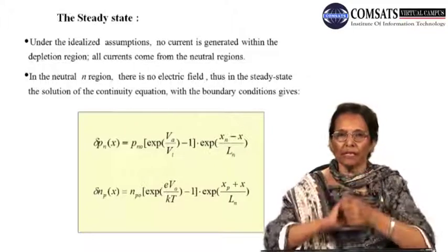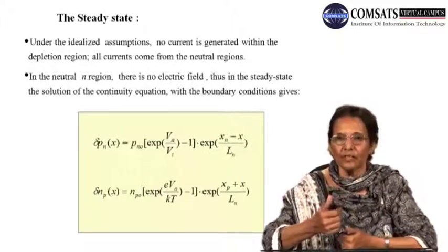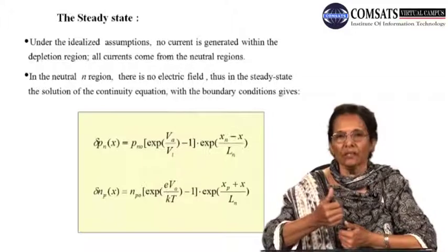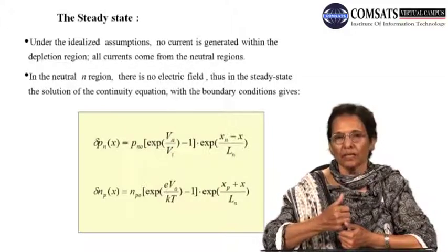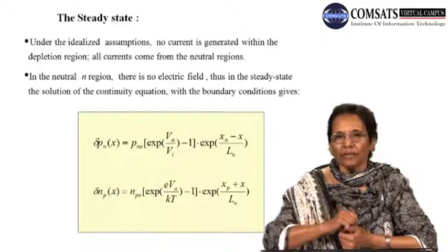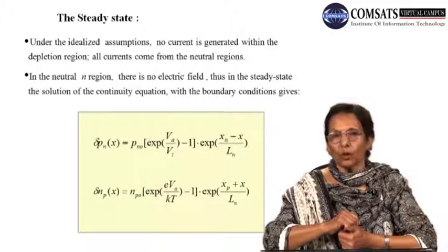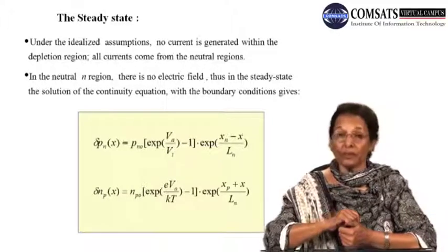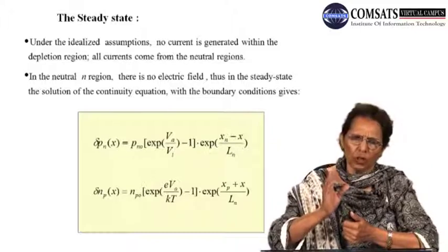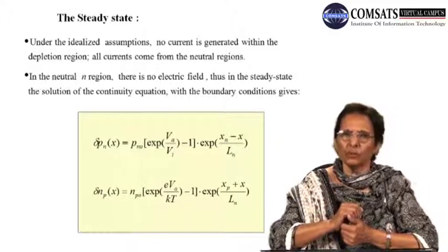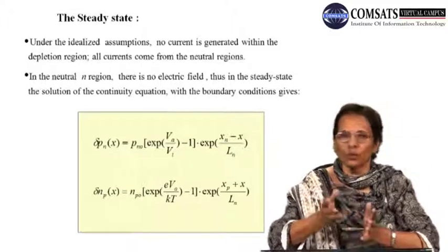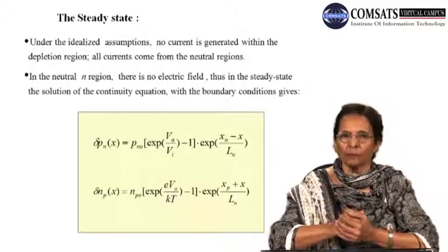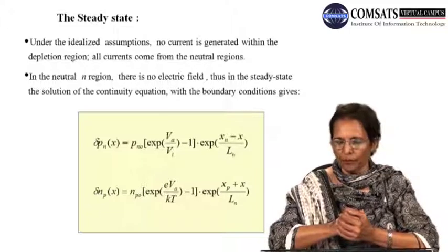Obviously they will recombine, and hence injected electrons start decreasing in numbers. Their decrease in number obviously depends on how strongly the P-type region has been doped, or the doping concentration of the acceptor atoms in the P region.